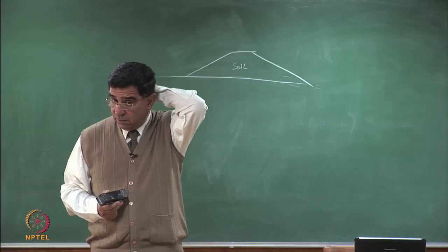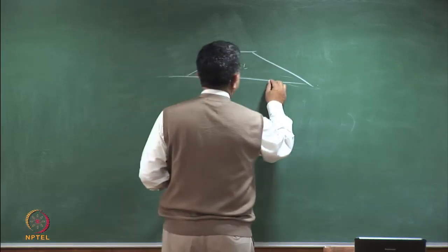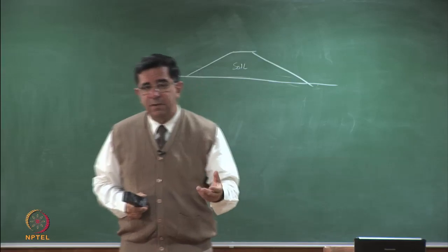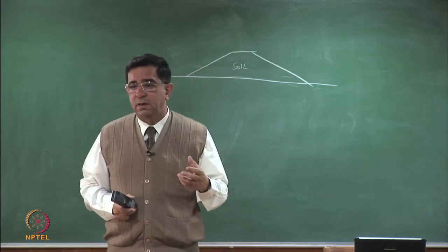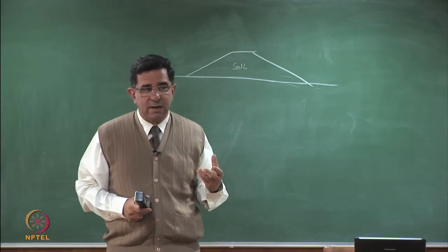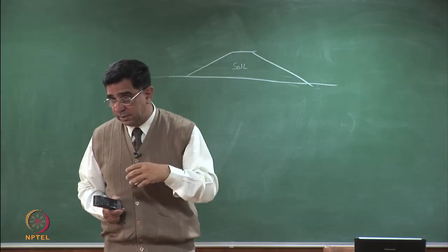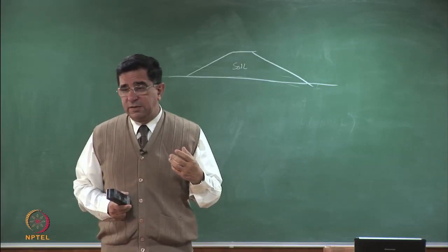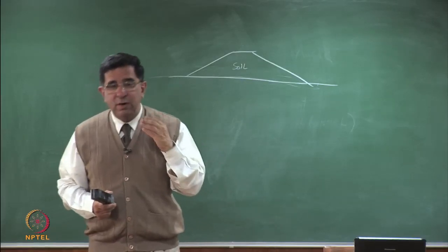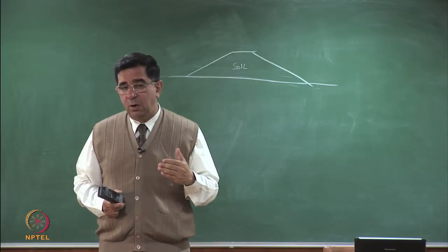If I have clay, how will I do the test? Again, I identify a borrow area, I bring the sample to the lab, I do the shear strength tests on as compacted samples. They can be as compacted or they can also be as compacted then saturated when I am simulating seepage, if I am expecting any seepage. What tests will you do on clay in the laboratory?